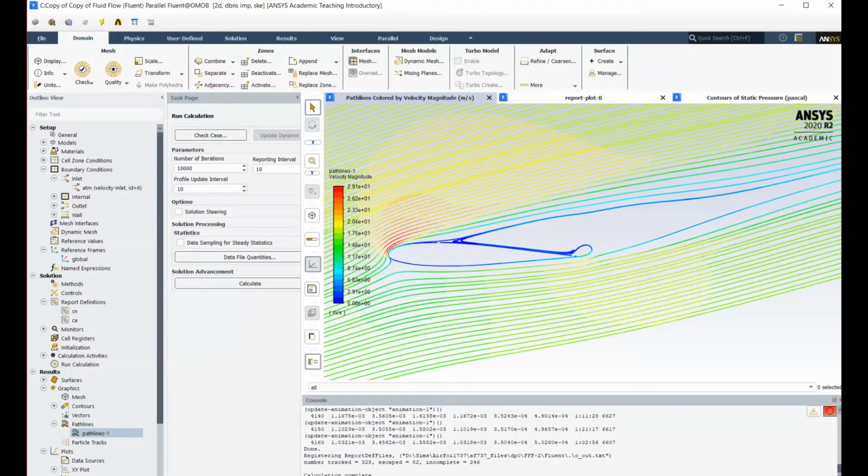The values came out very well. If you remember, the lift coefficient is practically independent of the Reynolds number. What will be important is the drag coefficient. When you start to calculate the viscous flow, it's very sensitive to the Reynolds number. Viscosity is the main source of drag, so it is influencing it. Okay, so the lift is basically not sensitive to Reynolds number. You can see that it's the same for all cases.